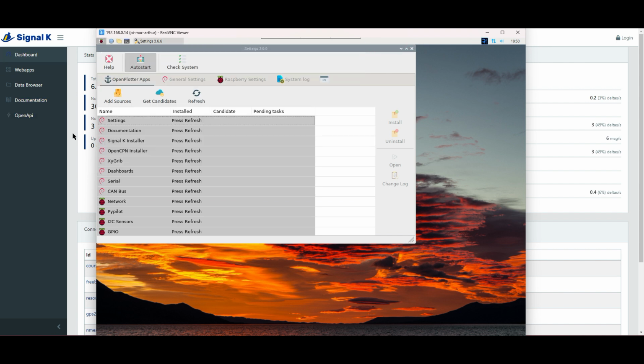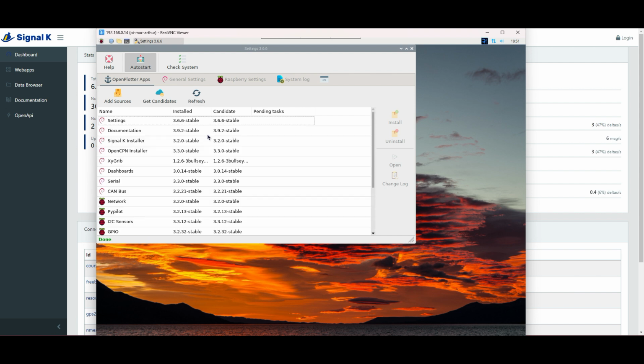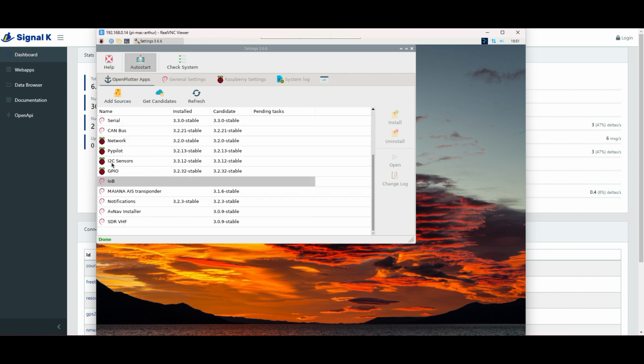You see also in the background already my PC browser accessing the Signal K server, because this is the quickest solution. We also have several other items here which are necessary on OpenPlotter to get data to our Signal K main system. I2C for the I2C sensors, GPIO for one-wire interfaces, or if you even want to connect a general pin.